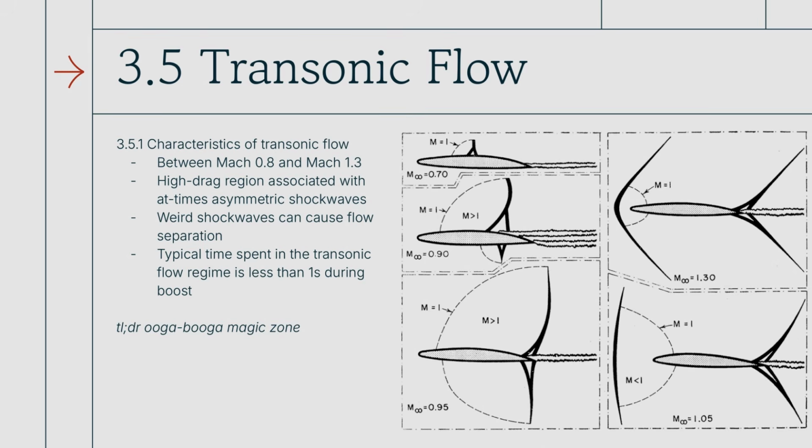And this will really mess with your flow. Maybe it will make the flow very chaotic. But essentially, the flow gets really weird. And so you either will lose lift or you will gain it. So that's why there's not really a good value here. I can't just tell you, oh, it's that, because it always depends on the geometry of your airfoil.